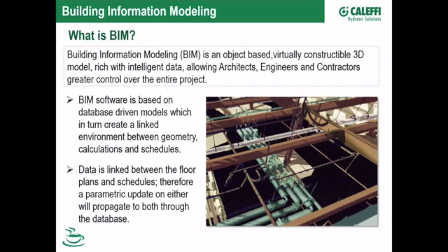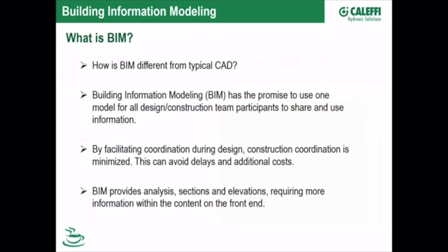So what is BIM and how does it differ from typical CAD? Well, first of all, CAD is vector-oriented. Whether it's used for architecture or engineering, it's primarily just a grouping of lines to represent your design. Sure, you can set layers to differentiate disciplines and purpose, but at the end you're left with a static vector-based image. With BIM, the software controls the classification of objects because that's how they're defined. And there's intelligence embedded within those objects which can be used by engineers and architects to provide the users with information about the building model.